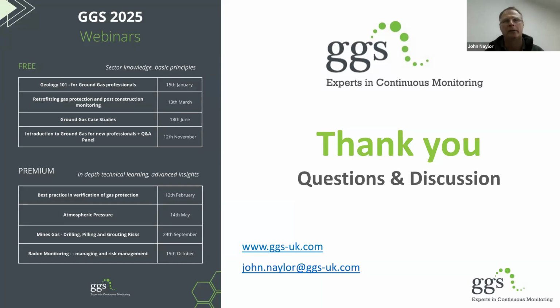Again, with VOCs, it's not really in the guidance, but it's usually a chronic effect that we're worried about rather than acute effect. So you might manage that with air ventilation changes. So an active system. Again, that will mean managing, maintaining. I would say there's nothing wrong with doing a few compliance monitoring points going forwards to make sure that's resolved, if it's a declining source term or it's being removed.